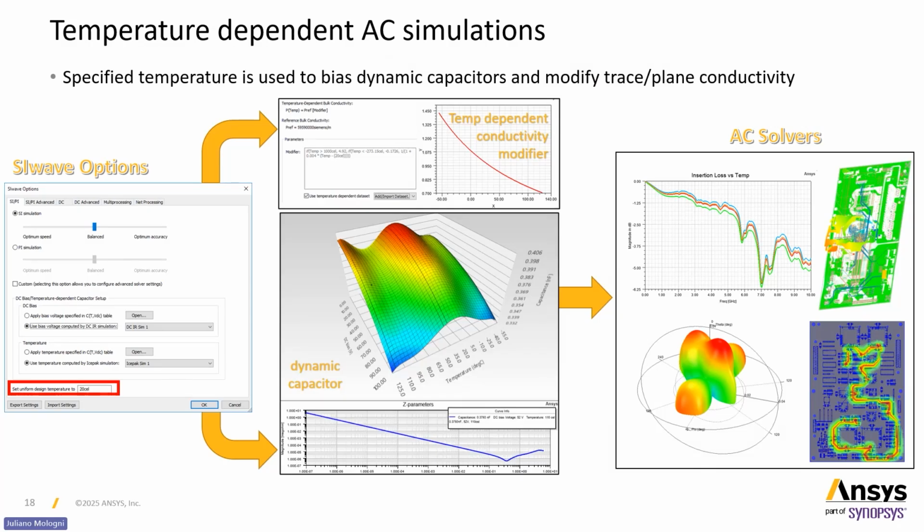And one thing that most people don't consider during their design is the temperature effects, right? Sometimes you design a PCB and that PCB goes to the underhood of the vehicle where temperatures are really high. So you have not only thermal noise, you have jitter on your signals, you have different properties for dielectric, even for your copper, right, your metals.